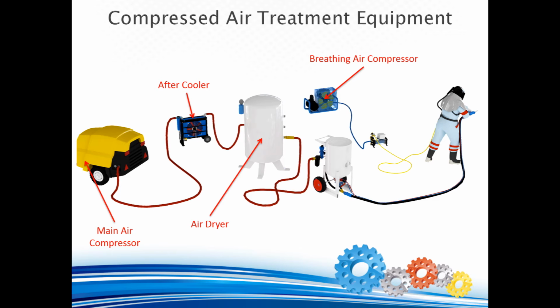Moist abrasive media can adhere to the internal components of blast equipment, and when it dries, it can be extremely difficult to remove. Water and oil vapors can also cause flash rusting on the surface of steel products, and oil vapors deposited on surfaces will cause paint and other coatings to adhere poorly or create early failures such as chipping and separating. For those of us in high humidity areas, the aggravations created by moisture are compounded.